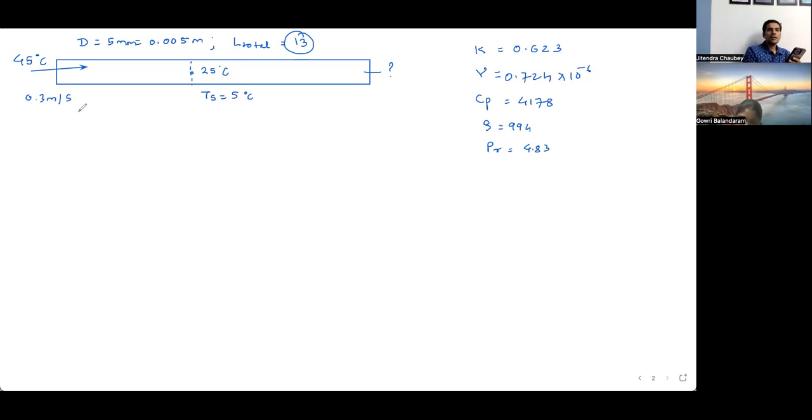See, in this case, the fluid is losing heat, so you use Q equals mass flow rate times Cp delta T. We can use the formula m Cp dT. We have got the cross section, so mass flow rate can be written as m dot, which is rho A v. It will be rho A v into Cp dT. This is the formula for Q lost by the water.